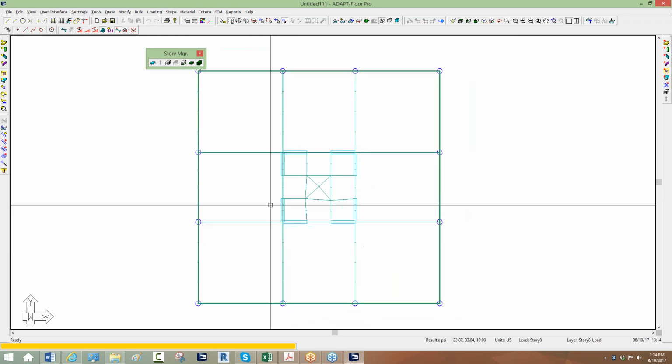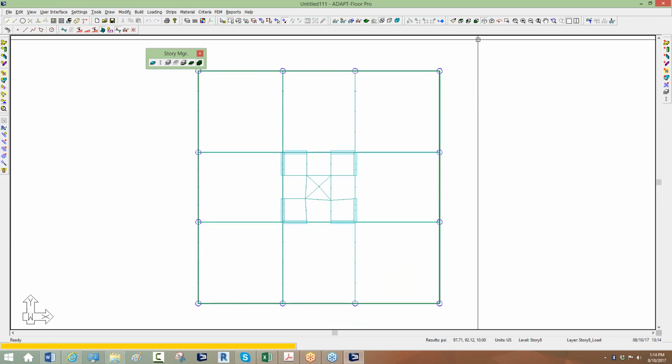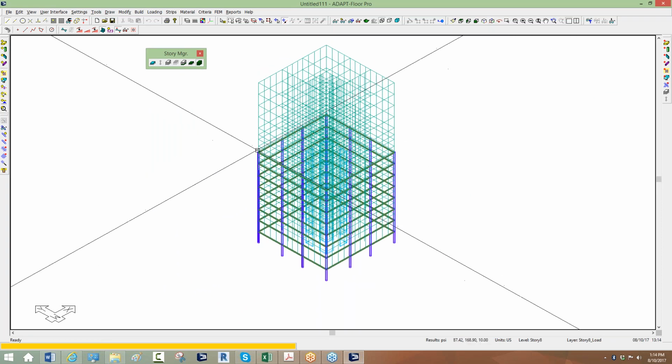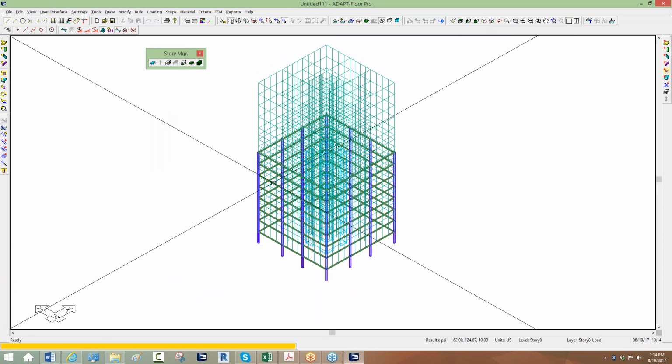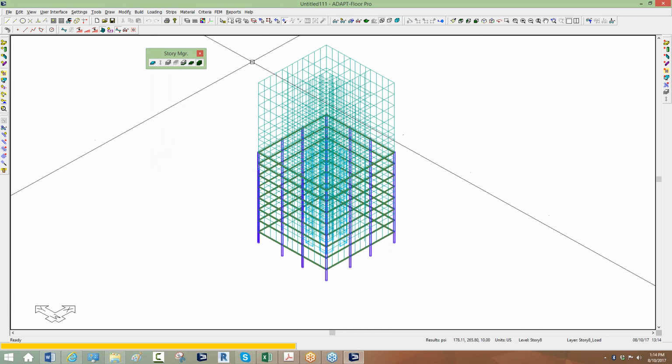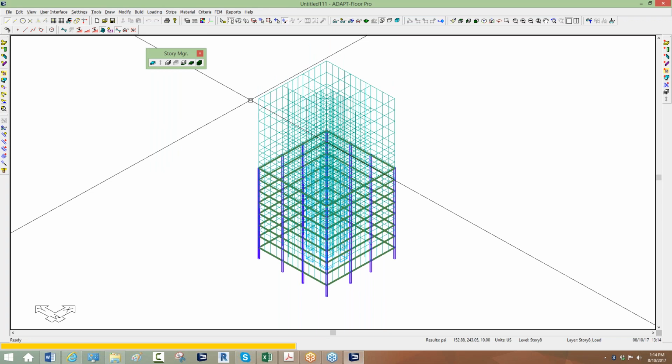And now the program produces the same model that was found in Etabs with all the loading. By default, it's going to show columns, walls, all the different components, slabs, and also the gravity loads. The gravity loads are externally applied loads. The lateral loads in the model, EQX and EQY, are not externally applied.